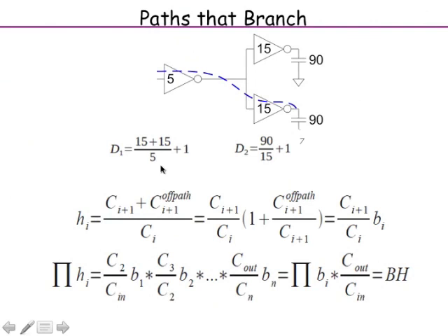So the way to solve these problems is to go back to the basic linear delay equation for each gate, as we just said. You set up the equation, you take the sum, you minimize the sum and you get the answers. We can also write it this way: the electrical effort of gate i is C i plus 1, which is the gate in the path, plus any loading off the path, that is the total C out for this gate, divided by its input Ci.